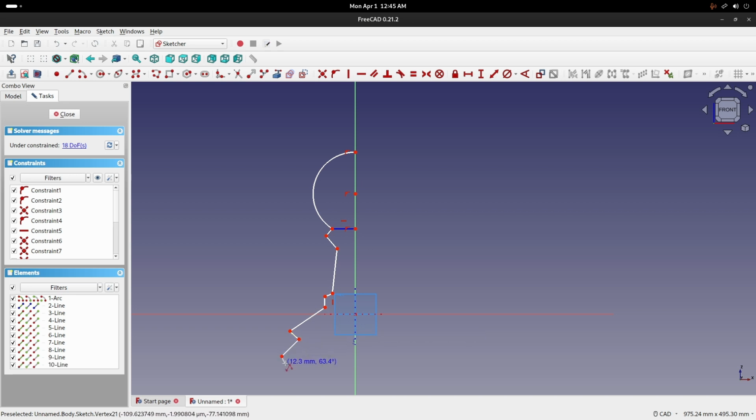So it can extend down like this because it has all the curves in these places. Then it kind of thins out. Always see when I am making the line in these angles, there is one point where I see this vertical line appear. It means my line is going to be created perfectly straight. Again, if you want it to be created on this axis, see on hovering, you get this yellow color. Just press. I want to complete this sketch till the curve.